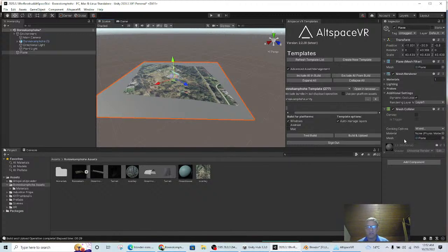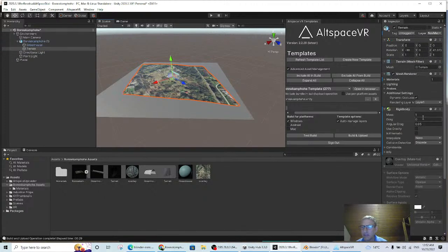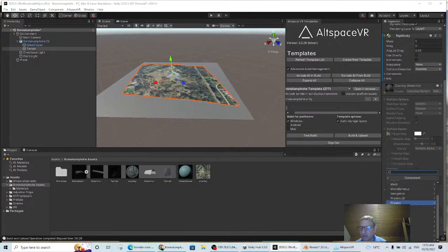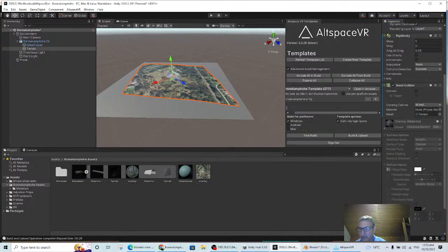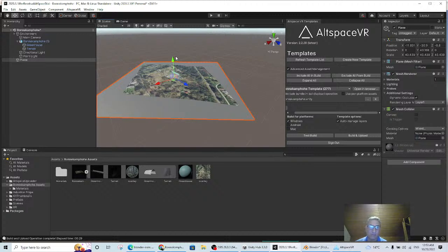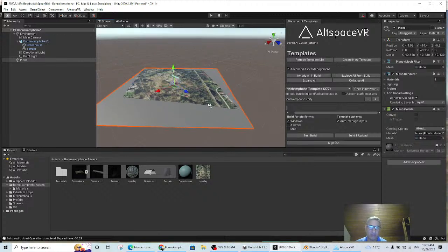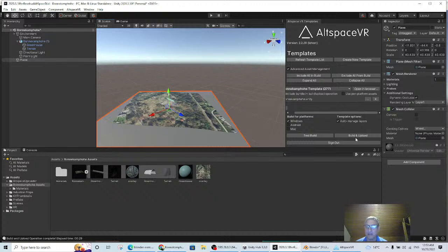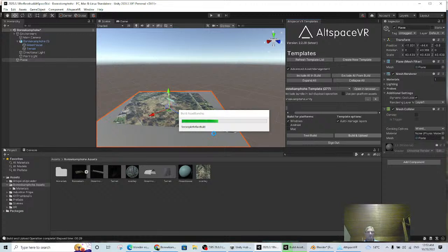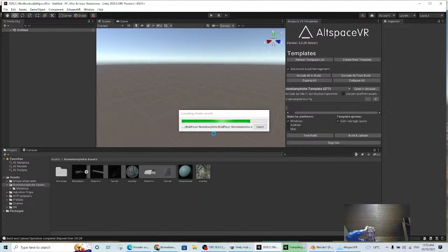So this has a mesh collider that's already built in, and maybe that's what's lacking here. It needs a mesh collider. Add a component, physics, mesh collider. Let's try that actually. Maybe we won't need this plane, but the plane has one, and if we fall through, we should land on the plane, which I'll keep underneath. But let me try this instead. So it must be a mesh collider. Somehow I've messed up. Let's try it. This could be very interesting.